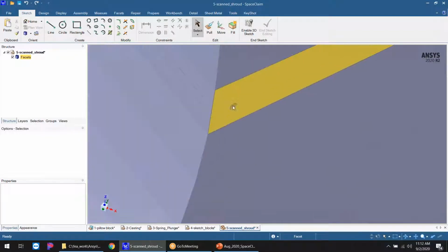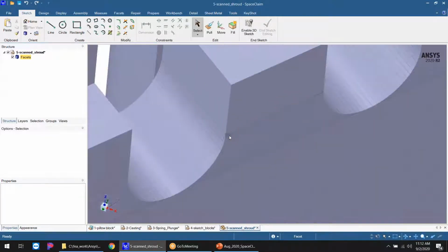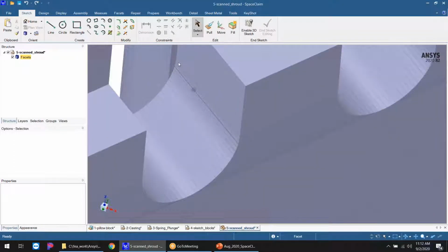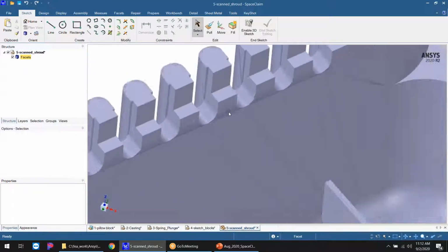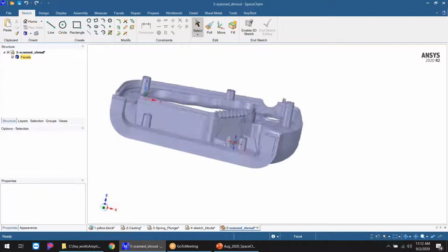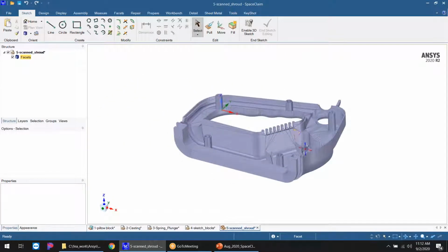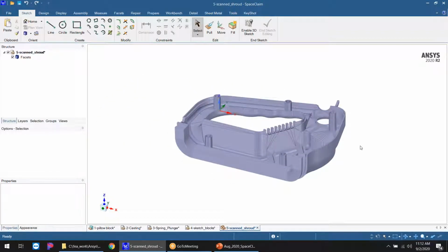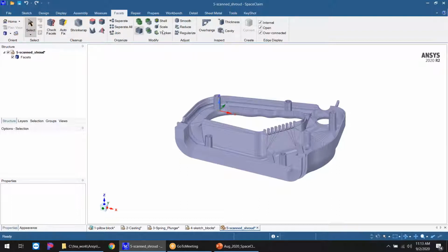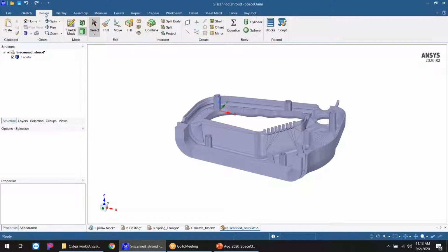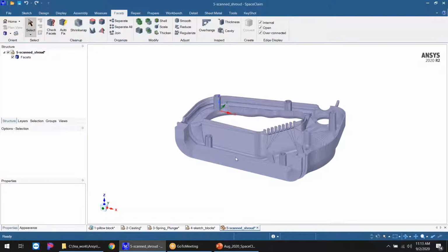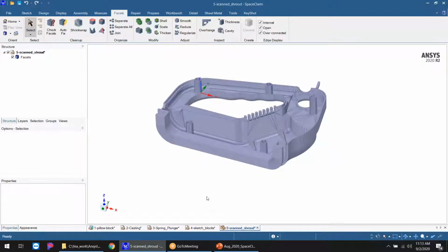And these triangles can be very, very small and very, very high aspect ratios, really narrow little corners and edges. Traditionally, a lot of the CAD tools, you open this STL file up and you have very, very limited capability. But for a long, long time, SpaceClaim's had a full suite of modifying this geometry. Everything that we're used to from the design tab, which is pull, move, and fill, we can do all of that with facets